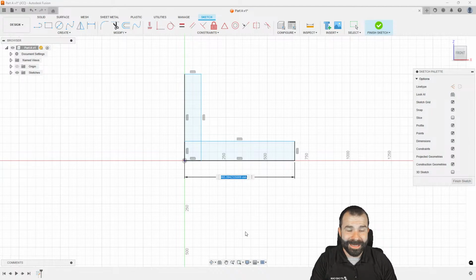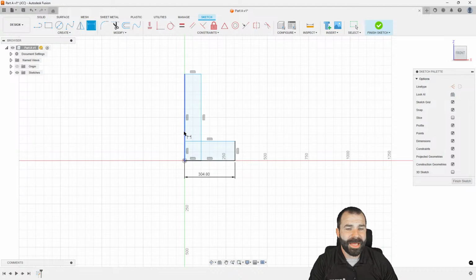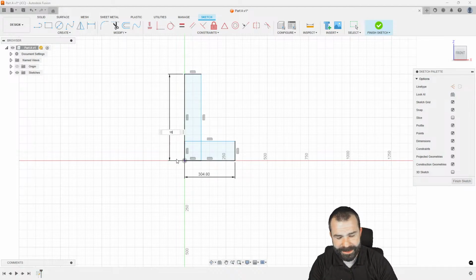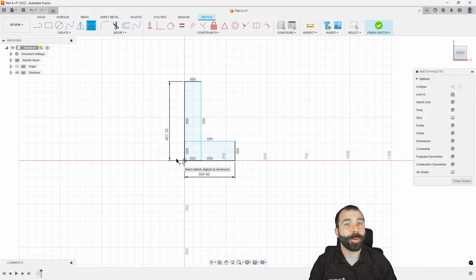As you can see right now, I'm in the metric system, or as some of us might say, the system that never gets you to the moon, right? In this case, I'm just going to type 12IN. This is a tip for a lot of you: you have the ability to type whatever increment you want to force into Fusion,